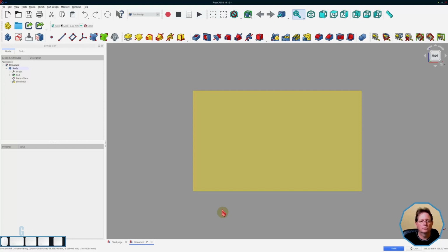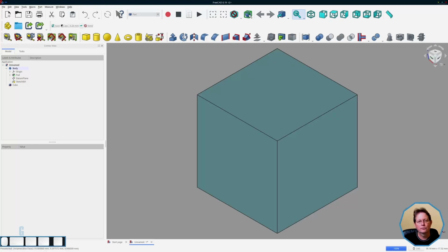Your sketch is in 2 dimensions. You can place your sketch elements in the x and y coordinates, but you can't change the z coordinates. All geometry that you place in the sketch is relative to the sketch's origin point, or 0, 0, regardless of where the sketch actually lies within the 3D coordinate space. FreeCAD automatically translates the coordinates in the sketch to the global coordinate system so that the model is created correctly. After all that waffle, let's have a look at how this actually works.